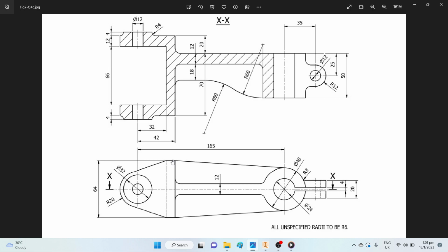Well, technically you're not wrong, but according to this particular curriculum and the way the 3D models are being marked, if you do not follow the dimensions given in the drawing, you will lose marks. So if it says from here to the back edge 32, you dimension it accordingly. This goes in line with the philosophy that in the event the designer ever changes this number, you will be able to go back to your sketch and make amendments with minimal disruption to all your other dimensions and design errors that would be caused during the rebuild.